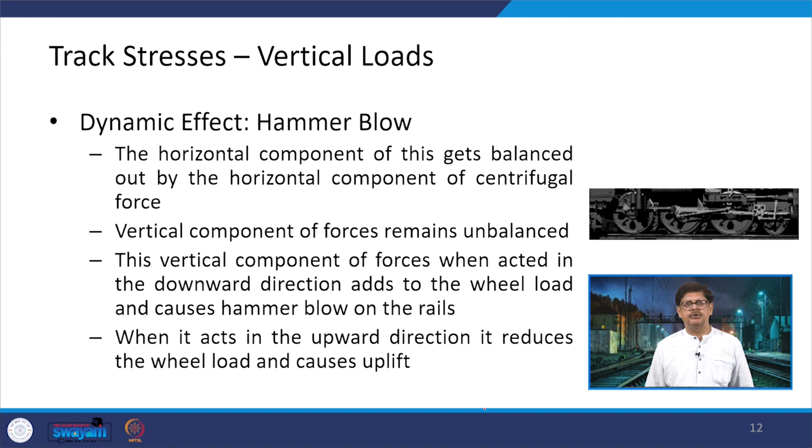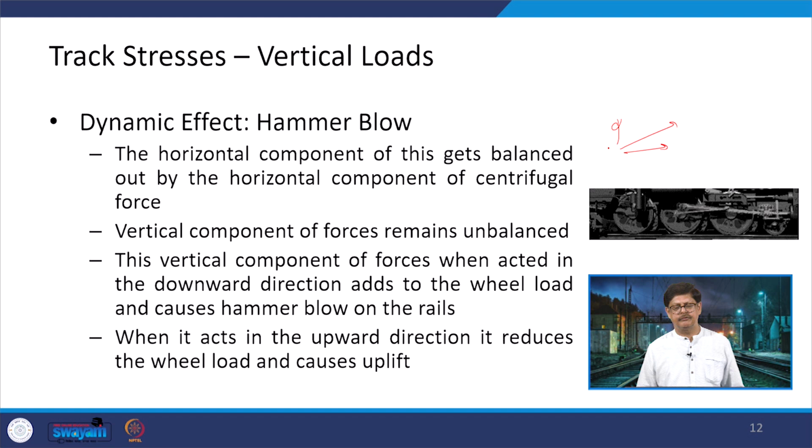Now, the horizontal component of this gets balanced out by the horizontal component of the centrifugal force. When we talk about the centrifugal force which is acting outwards, if we take its components along the horizontal and vertical axes, wherever the disc is placed, there is a balancing effect. The vertical component of the force remains unbalanced, while the horizontal component gets balanced.